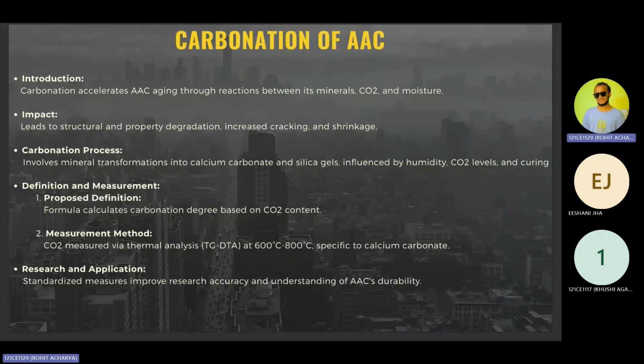Moving on to its impact, the impact of carbonation on AAC is very significant. It accelerates the aging process of AAC, which leads to structural and property degradation. Over time, what has been noticed is that it can result in increased cracking, shrinkage, and overall reduction in the material's durability and strength.